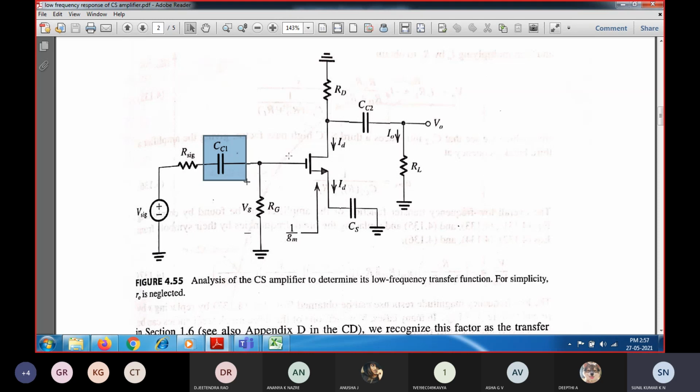So if the coupling capacitor is considered as an open at the initial frequency, nothing of the signal voltage will appear across the input side. If nothing is going to the input side, and since you also have a coupling capacitor of very large value, obviously no output voltage will be coupled to the output side.